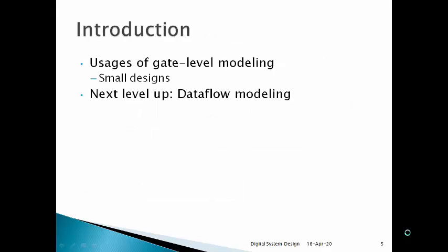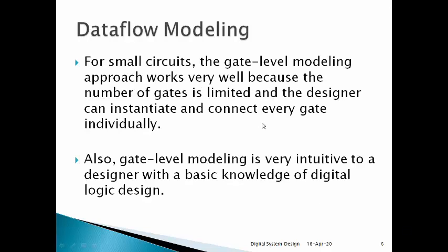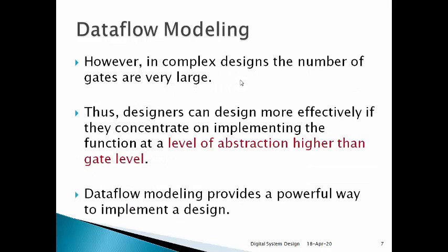Now starting from the introduction, we have studied gate level modeling, which is practically used for small designs. Now the next level up: Dataflow modeling. For small circuits, the gate level modeling approach is good because the number of gates is limited and the designer can instantiate and connect every gate individually. Other benefits include that gate level modeling is used with the very basic level of digital logic design.